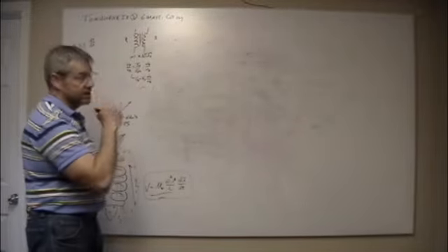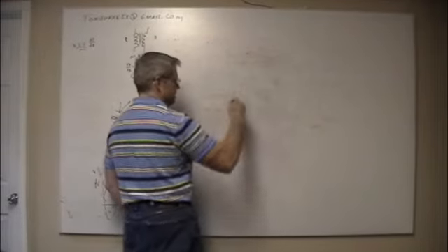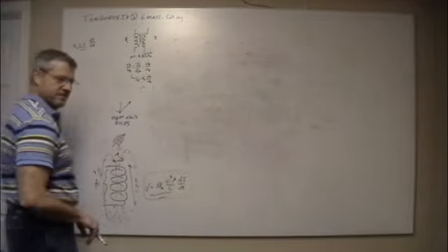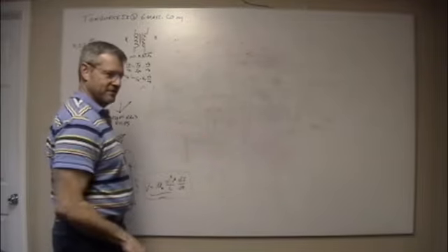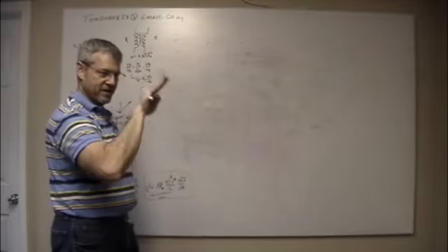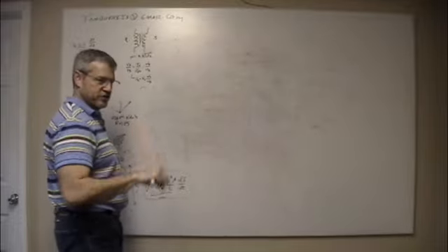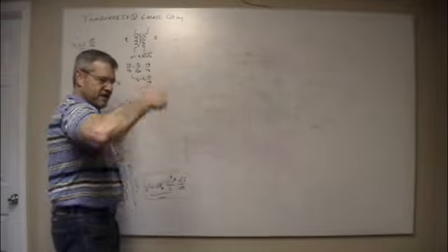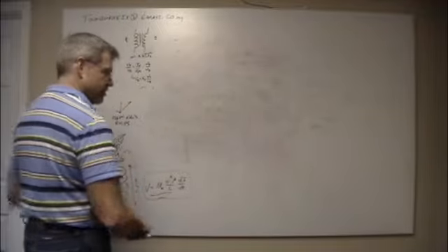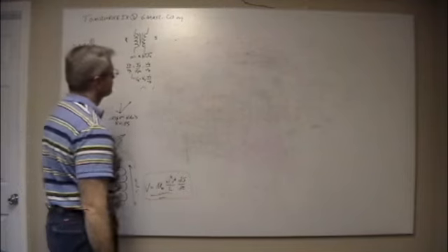There are some that are magnetically latching. You can do the circuit such that when it hits, it energizes itself. So you can kick it and just walk away, and it'll stay latched. And then you don't have to keep power going to it. It feeds itself. And then you do a power interrupter to kill the power and make it unlatch. There's some that are magnetic, and when you hit them, they latch, and you have to actually hit them again with the opposite polarity to unlatch them. Yeah, they use those in space, because you can latch them and walk away from them. No power used. Stays latched. Oh, yeah, that would make sense.